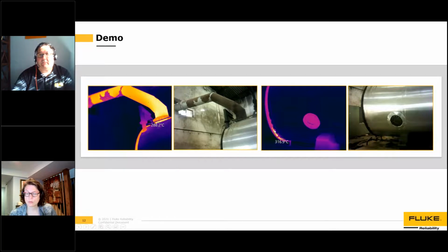That's where a thermal imager really proves its worth. And a fixed thermal imager is, like I mentioned previously, continuous eyes on the target. So if you don't have the ability to stand and watch the target over a full cycle or for many, many hours during a day with a handheld, this is an extra pair of eyes and an extra set of data collection tools for your arsenal.